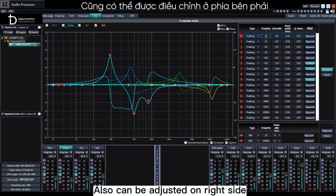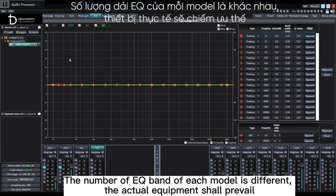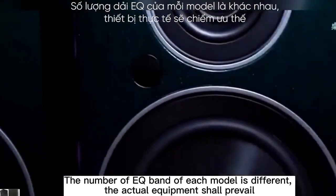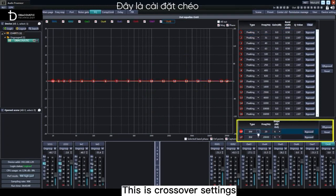Also can be adjusted on the right side. After finishing the adjustment, click to enable multiple band EQ for each input and output channel. The number of EQ bands of each model is different. The actual equipment shall prevail. Each channel has 6 types of filter options: peaking, notch, the first all pass, the second all pass, high shelf and low shelf. This is crossover settings.